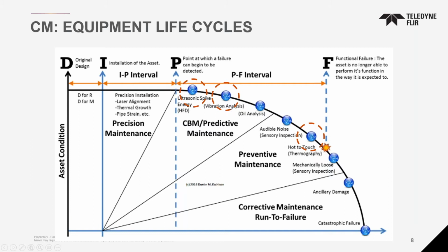I'm not going to be talking about vibration, but if you ever need information, we do have vibration sensors that can monitor vibration of equipment installed at various things. So it gives you kind of an early warning sign. If something was badly aligned, or there's a wearing out bearing in a motor and it's starting to vibrate more than normal, the vibration instruments will tell you that, so it gives you a warning. Then you can go and do the diagnostic with the ultrasound camera and or the thermometer.